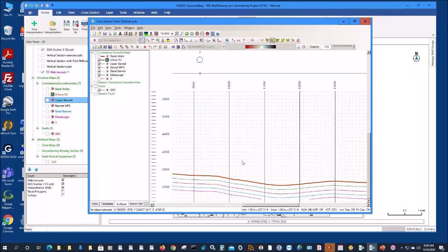So toplap, onlap, even downlap, of course, you could truncate against what's defined as a downlap unconformity. And then the channel form unconformity, incised valley or channel, where you can constrain the marine units by a flooding surface that is present across the entire area, again assuming that you believe there's concordance there. Then the channel will truncate those and you'll get an accurate rendition of where those truncations are on the map.